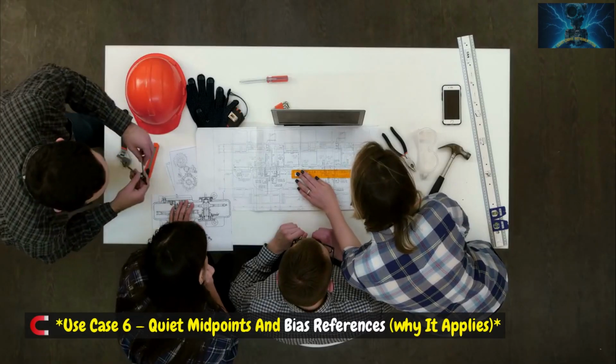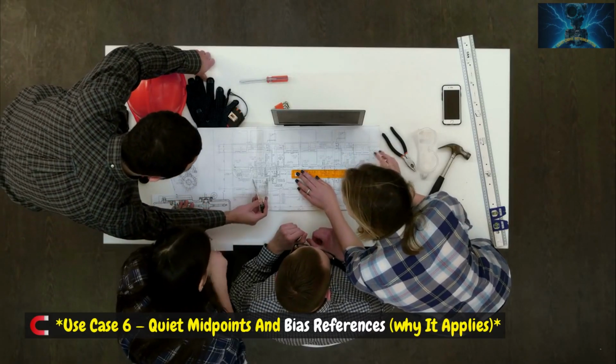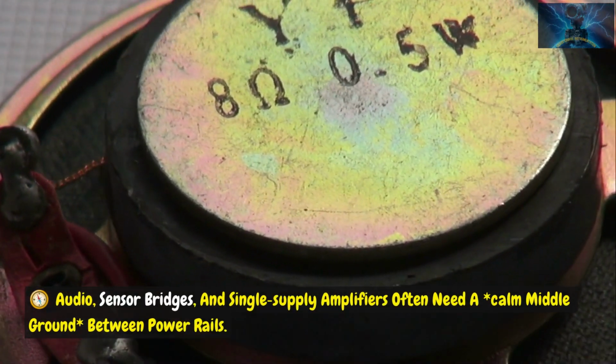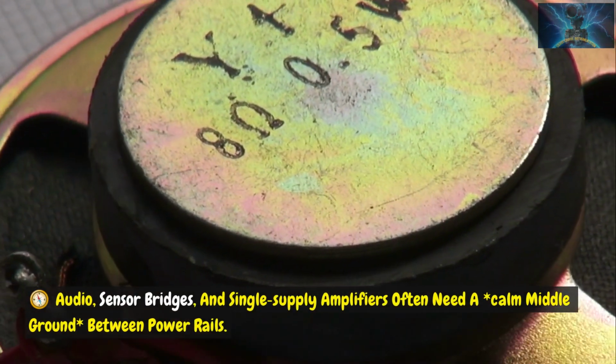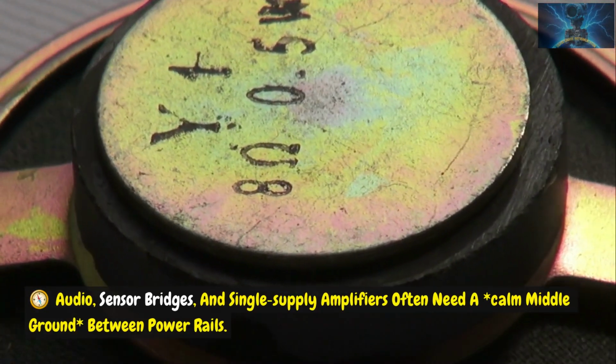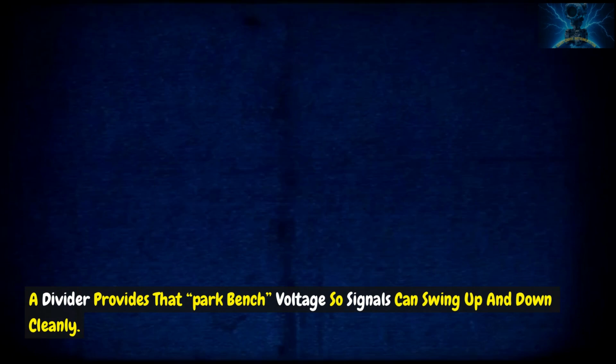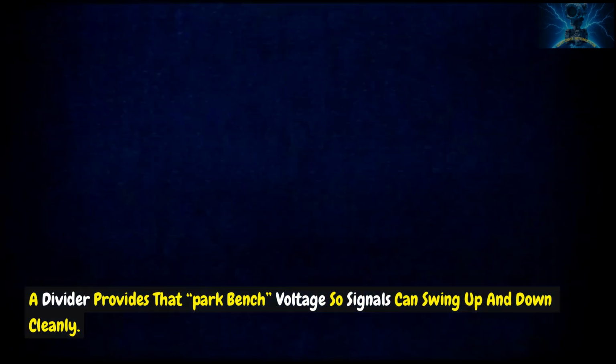Use case 6: quiet midpoints and bias references. Why it applies: audio, sensor bridges, and single-supply amplifiers often need a calm middle ground between power rails. A divider provides that park bench voltage so signals can swing up and down cleanly.